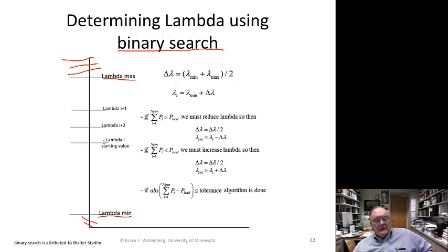And all I'm going to do is start halfway between. So halfway from there to there. The halfway point is right here, and I'll test it. And when I test it, remember wherever that value of lambda is, then I extend it across all the incremental cost functions, and I get a p-value. Well, if they're quadratic, that's a very easy solution because the incremental cost is linear. This is a very easy thing to come out with p sub i.